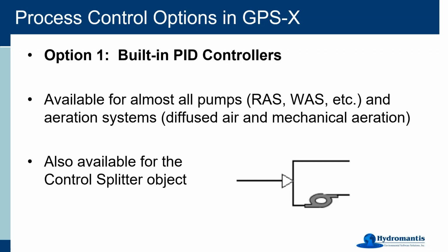So this is a regular kind of splitter. It controls the flow, comes in one side, goes out. In the control splitter, rather than setting a fraction, such as splitting it 50-50, you actually set the pump flow rate. So you set this side, the amount that goes through the pump side, and then all the rest of the flow goes the other way.